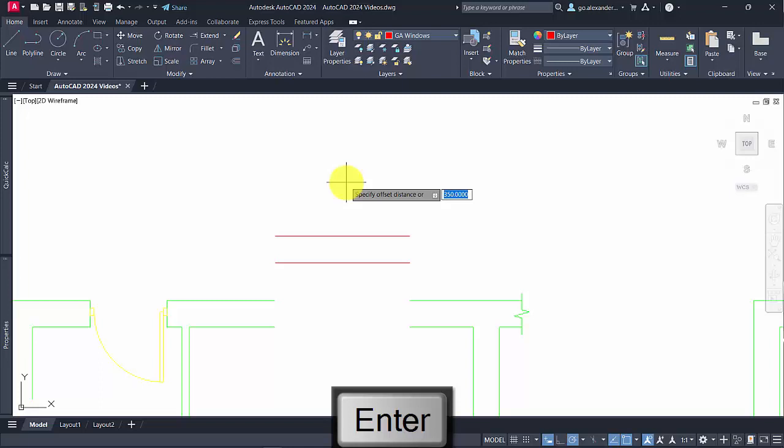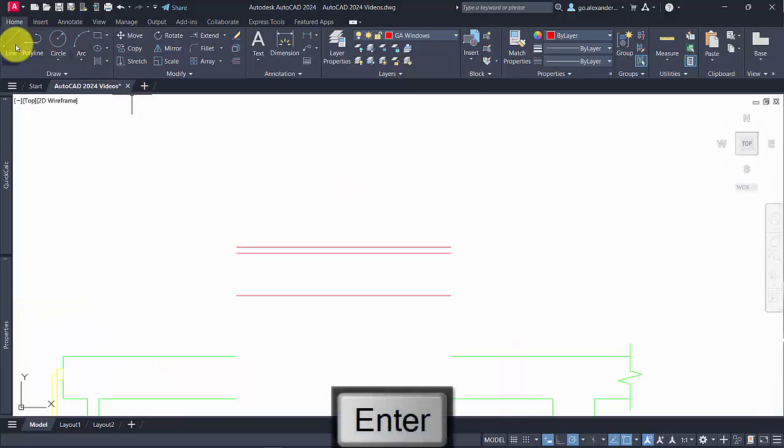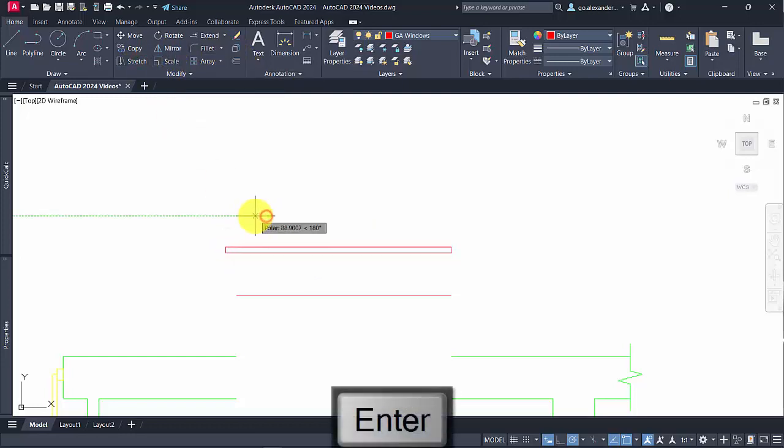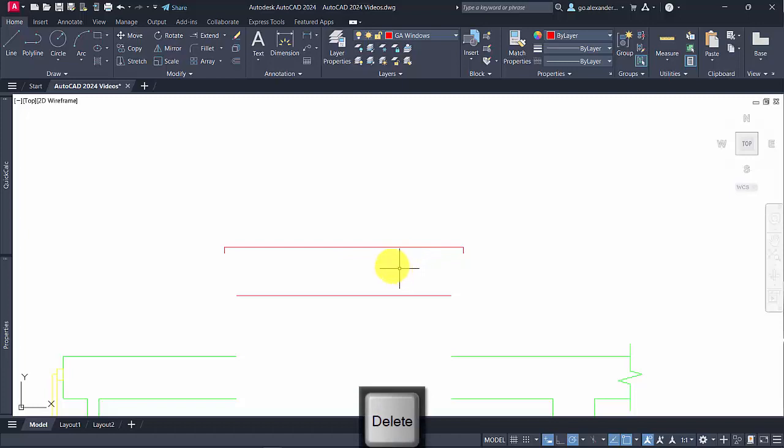Then the sill must sit out in front of that. The front edge of the sill must be 50 millimeters in front of that. And as well as that, we'll use a stooled sill that's built into each side of the reveal. So let's use the stretch tool at this point, and 100 millimeters would be standard there. And now we can delete that line because it isn't actually needed.